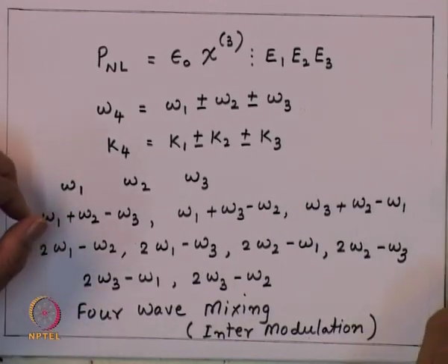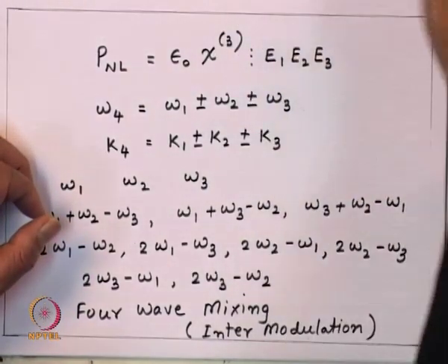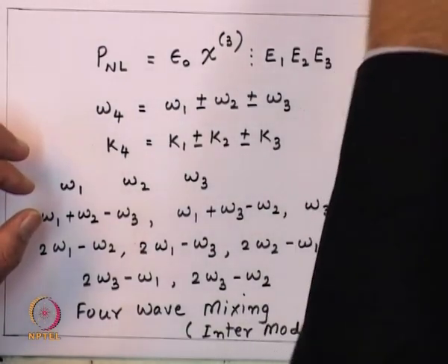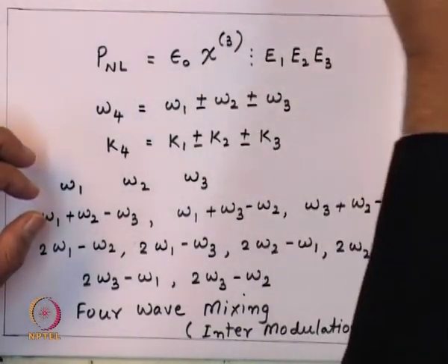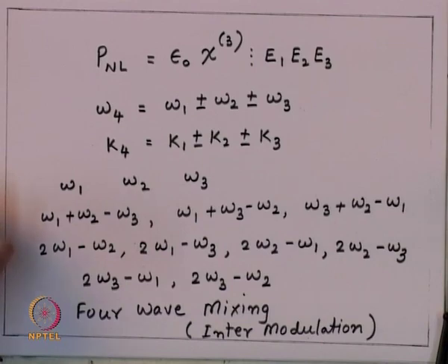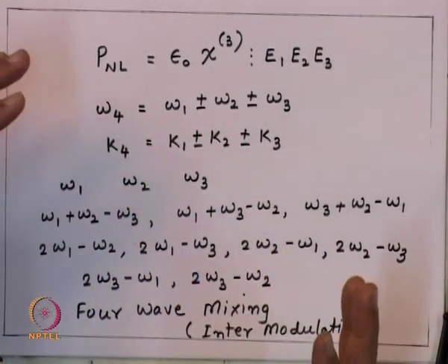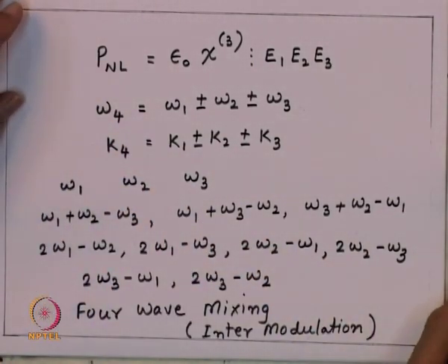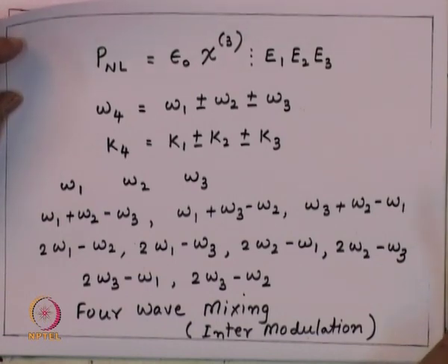Now you see that this phenomenon of 4-wave mixing, which comes because of that XPM kind of term, may affect the propagation of a WDM signal. So, let us consider a simple WDM system where there are 3 channels, and as we know in WDM the wavelengths are equispaced.